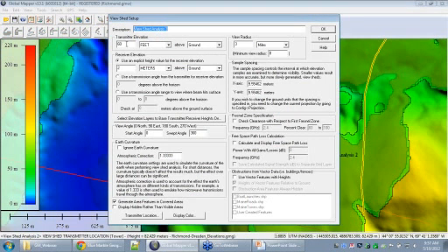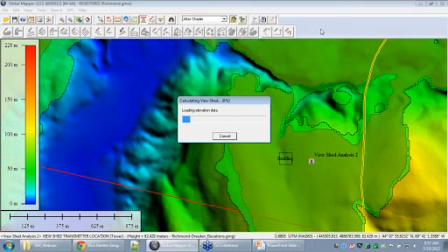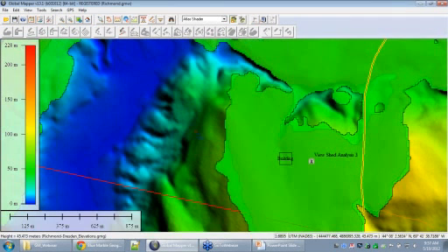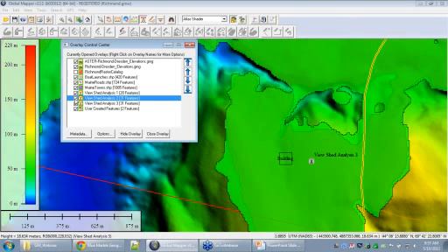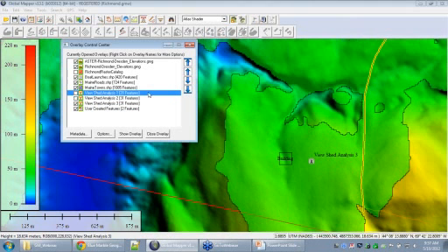If I plunk down in that same location, we can do that same view shed analysis, and this time we're going to end up seeing a shadow from that building in our output. So all of those 3D models that we drop in, if you're going to be hand digitizing those yourself just for some quick building footprints, or if you're going to be loading in pre-designed models from, say, a Collada file or an AutoCAD file, all of those different things are going to be affecting our view.